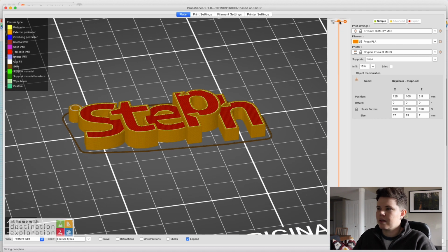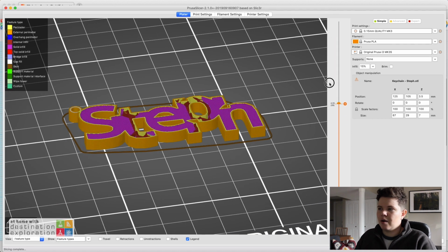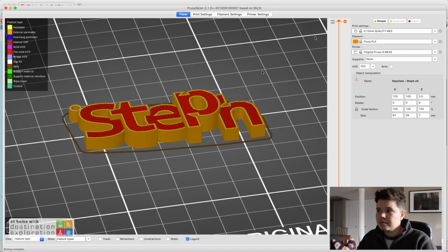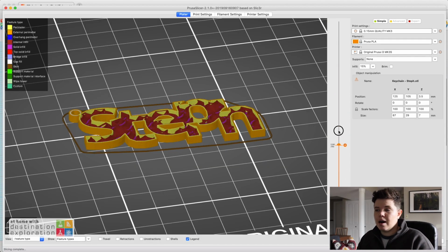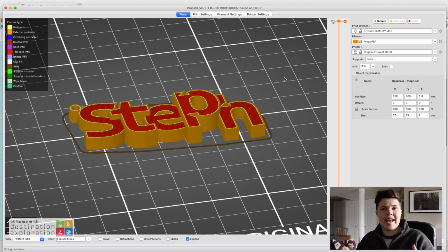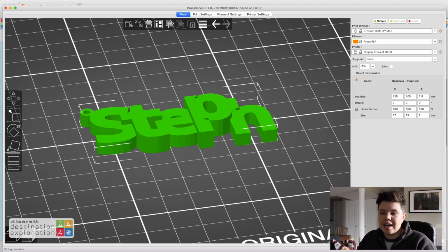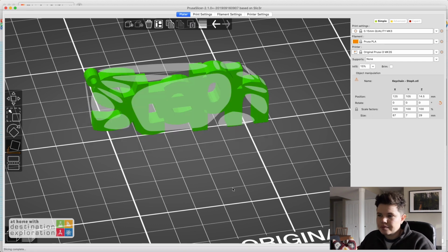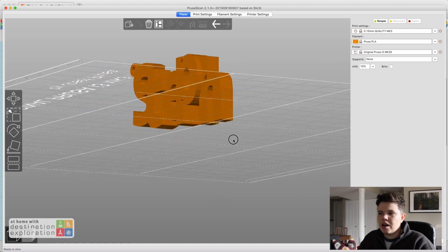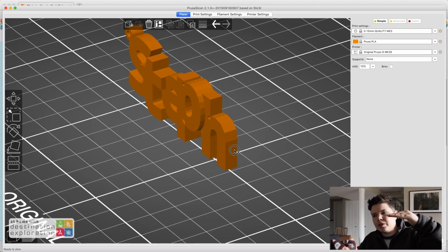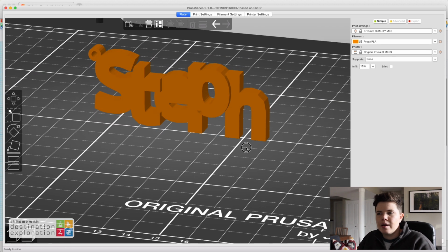Now, with a 3D printer, it's really important that we're aware while we're building how it's going to print. So it does print from the bottom up, and we wanna make sure that there's no overhangs or things like that, things that might be printing into thin air. So as an example, if I were to take this as the same design, it works, everything's great, but if I were to print it so that it was standing on its feet like this, so that as the printer grew, it started from the bottom to the top, okay?